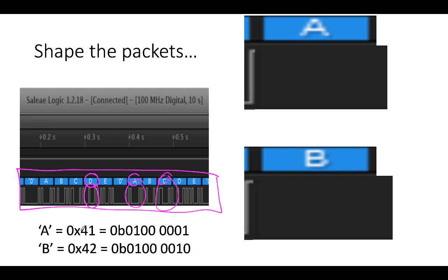If we're encoding these values from an ASCII perspective, which is a standard for representing alphanumeric characters, the A character is actually known numerically as 41, and it's represented as a 4 and a 1. Your capital B is 42, and it's represented as a 4 and a 2, like that. All right, so 4 and 2, 4 and 1. Let's take a look at how this works from a time sequence when it's actually being sent over that wire.